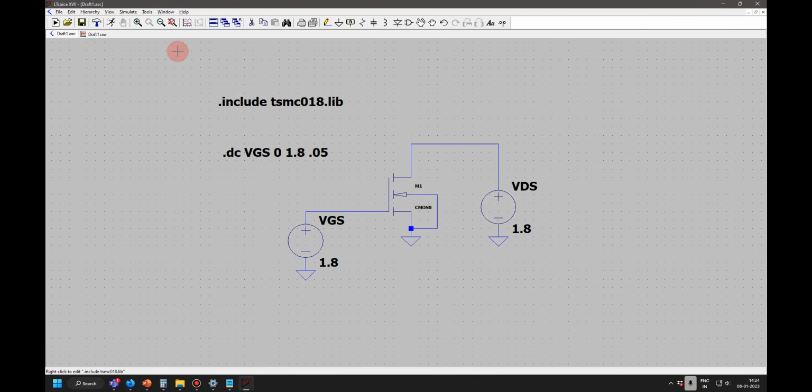Now I have to plot the current also, right? So for the current, you see this. This was voltage. For a current, you see there is one ring kind of thing which is coming, right? I see some kind of a handle and a ring. From where do we have to select current and voltage? You just take your cursor to those places. You will get these things coming up after the simulation.